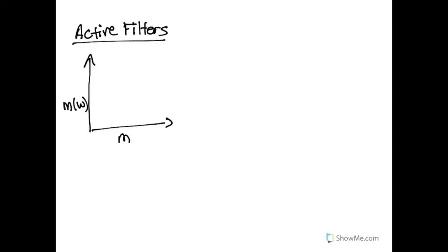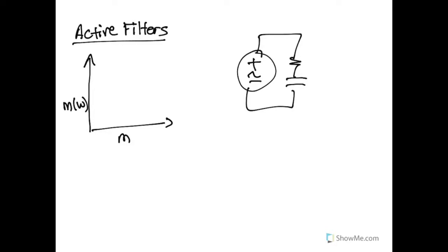In all of our preceding topics, one thing we haven't jumped into in big detail about is, can these filters provide any sort of amplification to our signal? So all of our basic RC circuits are passive components in our circuit. And while they can filter, the output of the filter is always going to be slightly less than the input. So whatever we measure across this resistor and capacitor is always going to be slightly less than what's coming out of that voltage source, because these resistors, capacitors, and inductors are all going to consume some amount of energy within our circuit.